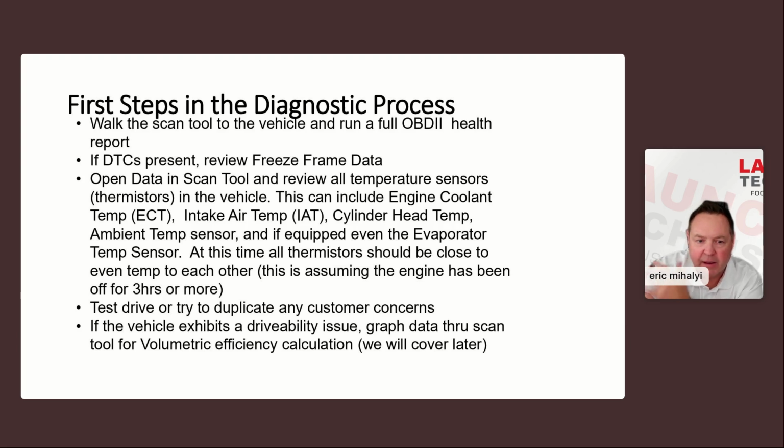And then they bring it in, and guys are saying, I don't have power at the AC compressor, and they're getting involved in chasing down wiring diagrams. And all that happened was somebody put a Pepsi up on the dash, and they spilled it, and they cleaned all the Pepsi off the top, but eventually it got down into the ambient air temperature sensor and then got into the connector and caused a bunch of problems, corrosion. Maybe it shorted out the sensor.